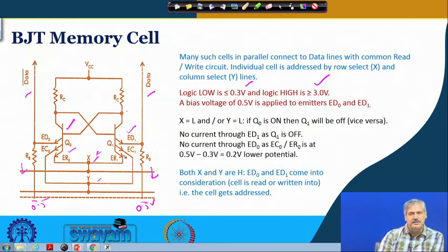This part is the major thing, and this is similar for your MOS-based cell or CMOS-based cell also, where two inverters will be connected back to back in a cross-coupled manner, like this, with the feedback coming in this manner. Similar things will be there for the other cases, which will offer a bistable mode of operation for this particular block.